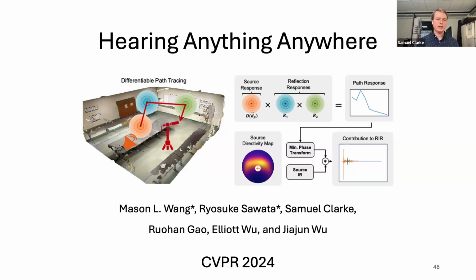So if we wanted to take this data and predict the sound field in a different room or outside, we can convolve these different impact sounds with a room impulse response of a new environment and predict what that would sound like. Obviously, the semi-anechoic chamber is not perfect, but within the constraints of a decent budget, we got the reverberation to have as little effect on the data as possible.